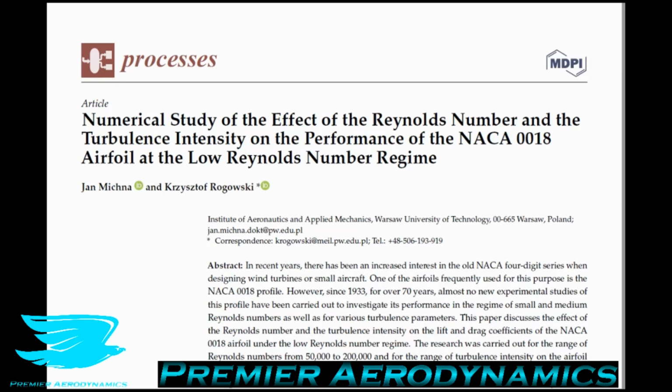And the reason why is because at low Reynolds number, this is where the turbulence that is created by either the surface roughness or introduced by the turbulence intensity level or by the Reynolds number really has a major effect because the flow is laminar/transitional. If you go to very high Reynolds numbers, then the turbulence intensity level is not nearly as important because the flow is already very turbulent, and that already means that it's acting in the way that it should, and increasing the turbulence intensity level doesn't really change that characteristic too much. So this is a very interesting region of Reynolds numbers to look at.